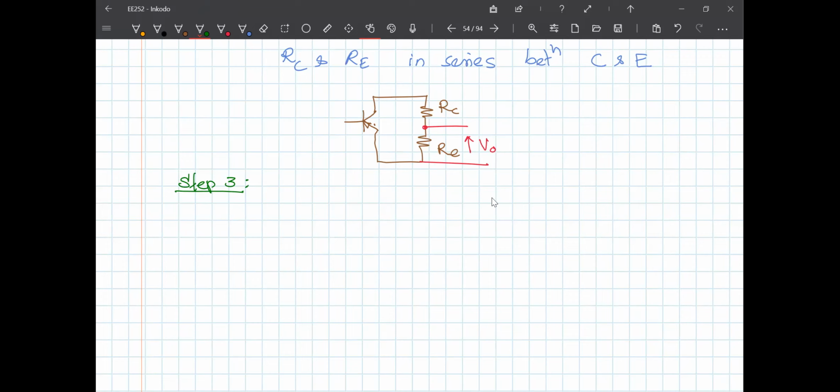If you are connecting the feedback signal to the circuit in series, then it should be a voltage, in which case you draw the first stage as a Thevenin circuit. But if you are giving the feedback in shunt, that means the input to the second stage is a current. So therefore you need to represent the first stage in that case as a Norton's circuit, right? Hope this is clear.